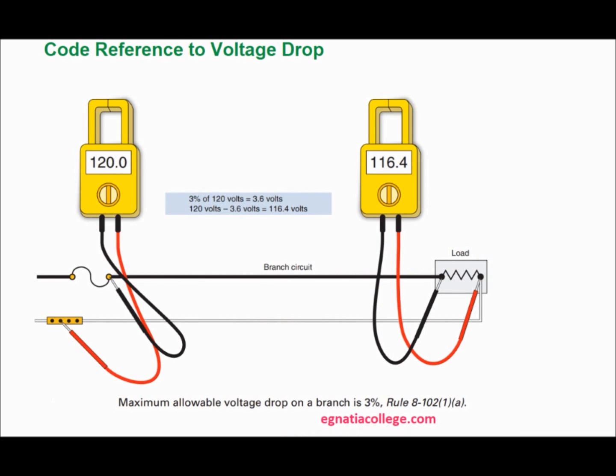Rule 8-102 states the maximum allowed voltage drop percentages. The voltage drop shall not exceed 3% in any feeder or branch circuit and 5% overall. This figure explains the requirements for a voltage drop that involves both the feeder and a branch circuit. Caution using high-temperature wire.